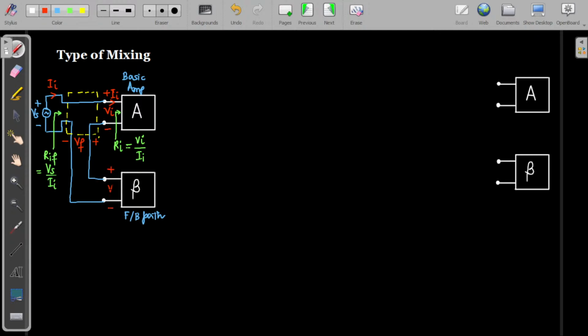ये आपका VF था. Okay, now in this VF you can see that बेसिक एम्पलीफायर के अंदर, ध्यान से देखना, बेसिक एम्पलीफायर के अंदर जो इनपुट करंट है और सोर्स से जो करंट निकल रहा है ये दोनों सेम है. सो फर्स्ट पॉइंट में क्या लिख सकता हूँ, पहला वाला पॉइंट कि द इनपुट करंट I input, it will be equals to the input current of the basic amplifier.